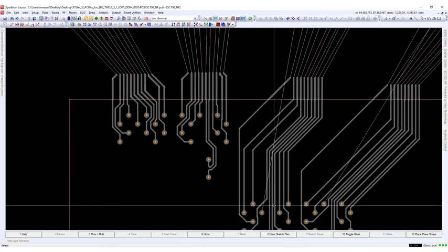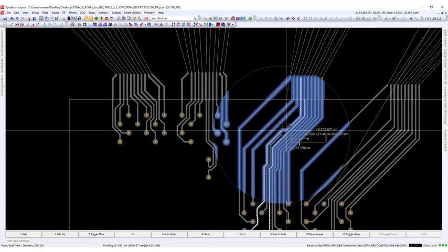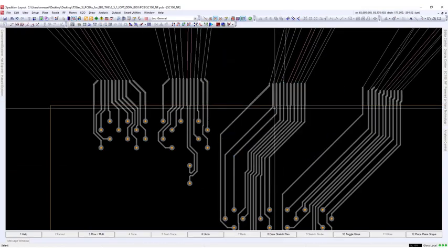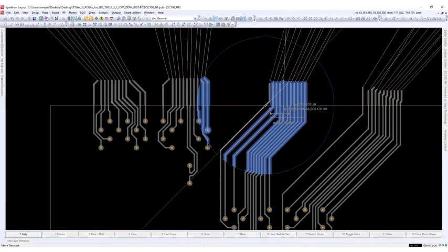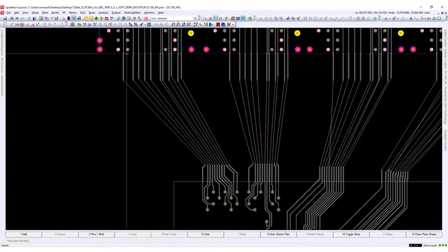Sketch Planner is also based on the sketch routing technology, and routing quality and following the layout designer's intent is most important. This means push and shove is not allowed. We see 2 open netlines which can be completed easily.